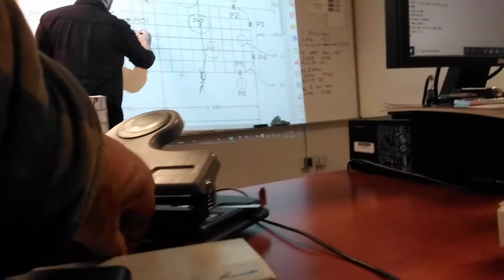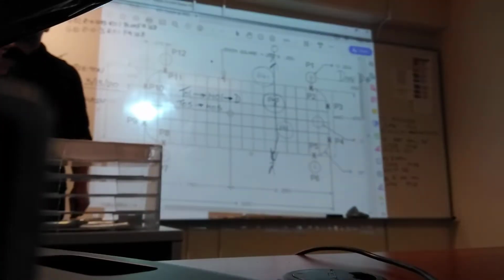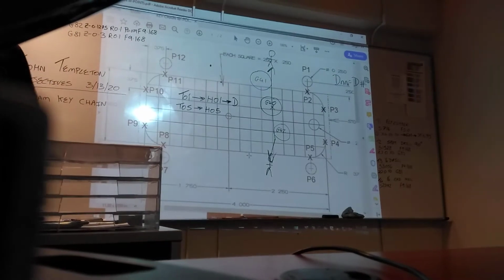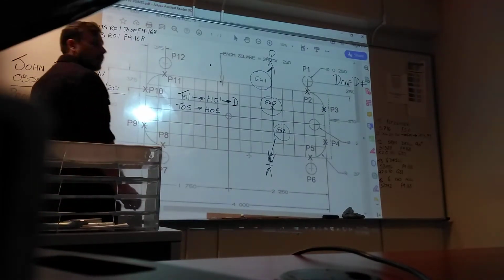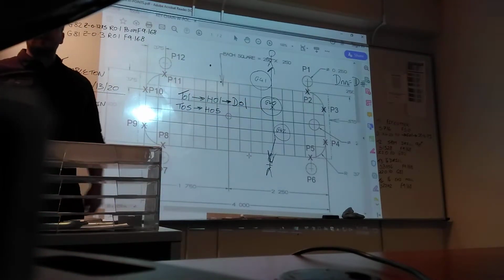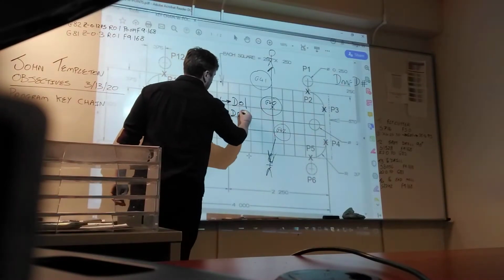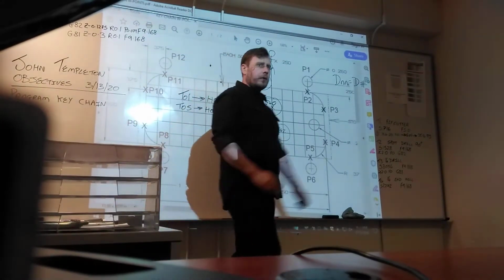Use tool 5, we use height offset 5. The D represents diameter offset. So if you're using tool 1, what D value are you going to use? Diameter 1. If you're using tool 5, you'll tell the machine diameter number 5.